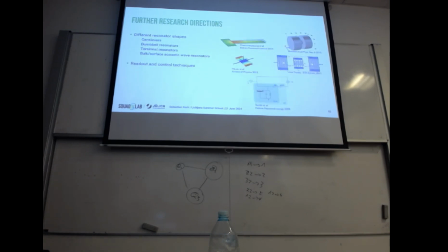So other possible research directions in this field. This is just one example. First, I could look at more resonators. There are cantilevers, like this one, where you just cut off one end. I've already done this. There's a factor of 2 in there, so you will get another factor of 2 in coupling. The beams get shorter, which is also expected, because the resonance frequency is much higher if you lose one end.